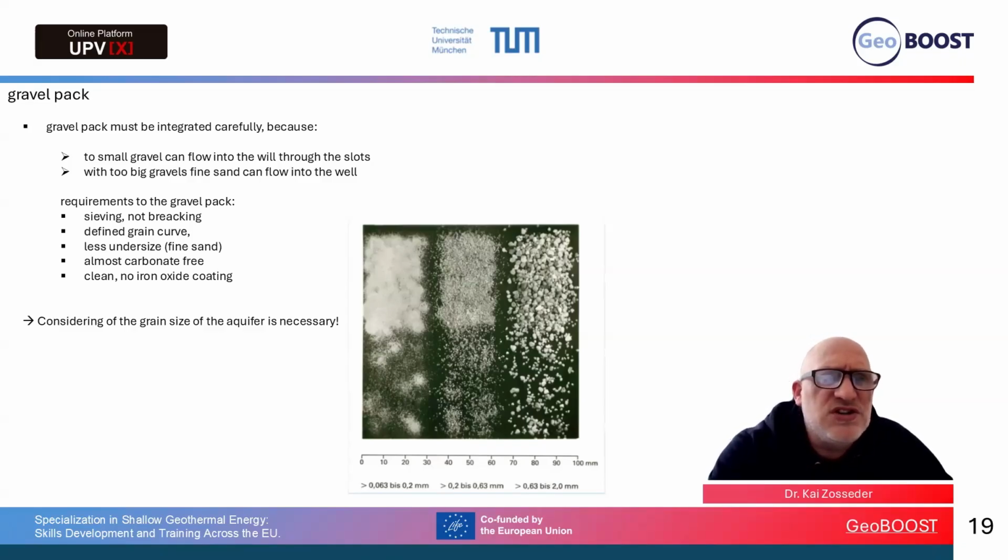So you should use gravels with the right size that is not going through the slots, and too big gravels actually cannot avoid that fines can flow into your well. So the gravel pack should also be safe, that it's not breaking and not cracking your filter section. You have a defined grain size curve. It should not be undersized. It should be almost carbonate free, clean, no iron oxide coating, so that you do not have a well alteration caused by your gravel pack.